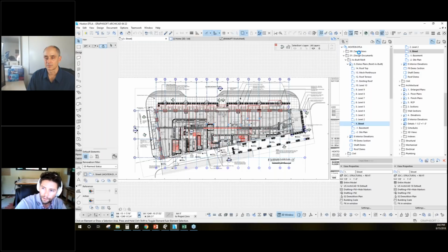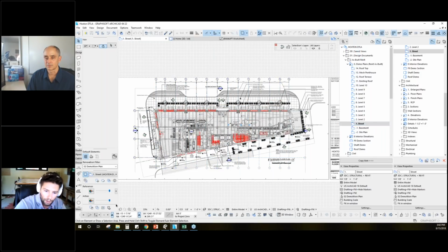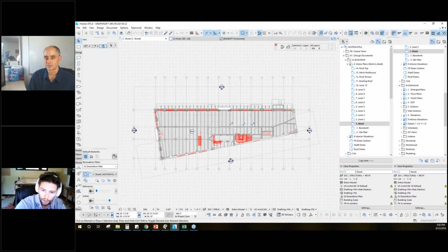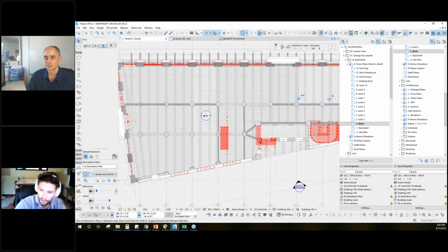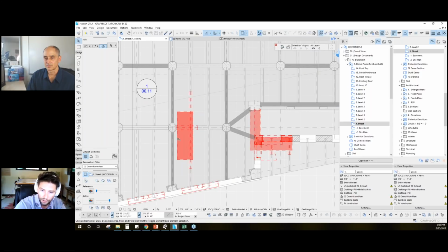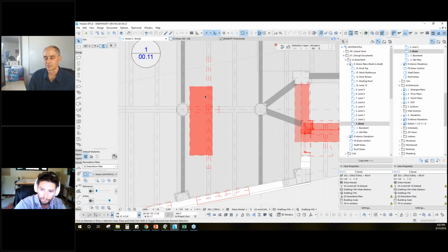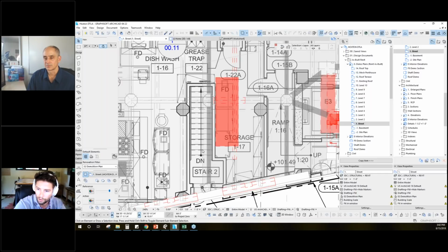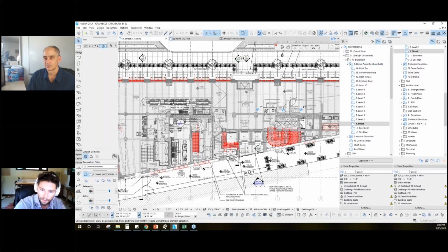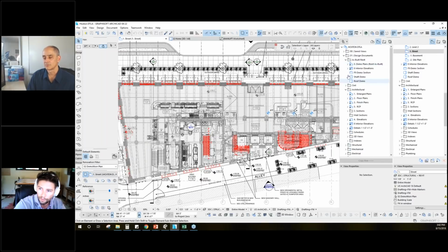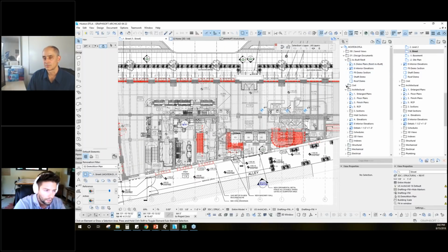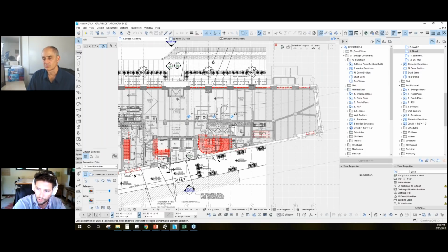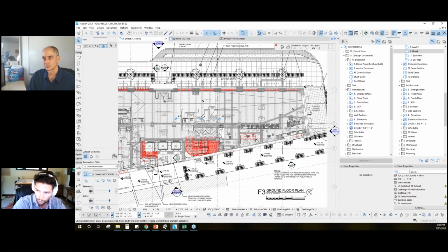And because of the structure in this template, there's a lot that we can do with that Revit model, which is actually produced from an as-built, going through and assigning the demoed layers and looking at where they're going to have to break off, demo specific beams to create new openings, through holes and stuff for new stairwells and all that. So it's just a way of starting to connect different types of content, in this case Revit versus PDFs, and using that as a way of reviewing the content, finding the issues, and trying to project where there might be some things we need to work out.